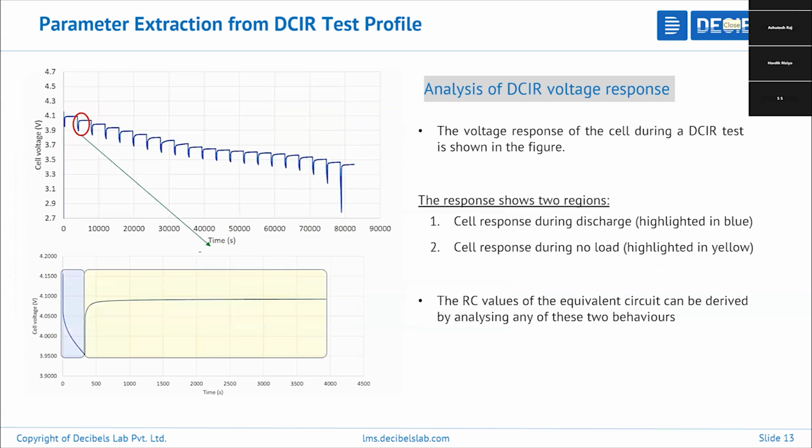Now in the figure, you can see the full SOC removal from 100% to 0%, and how your pulse is going on. At 100%, 95%, 85%, in all those pulses there will be some associated voltage drop. I have shown that region at a zoom level. You can observe it during your pulses and then during your relaxations.